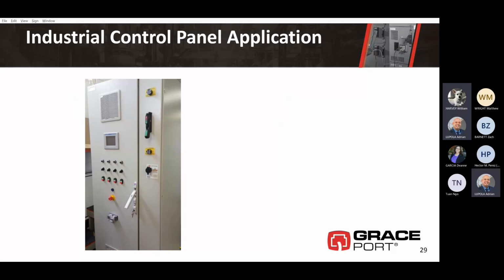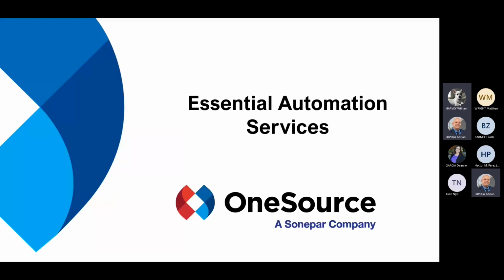If I turn the disconnect off, I'll see lights on the top. That lets the guy know there's live voltage coming into the panel. Down at the bottom, the switch is off. Or if I blew a fuse, I'd see 2 of the legs are still hot. One, the thing is off. I know what's going on. Right below that is the voltage test station where I can put the probes in and test. So you can do a lot of verification without having to open the panel and have people put the suits on. So that was the quickie application about downtime.